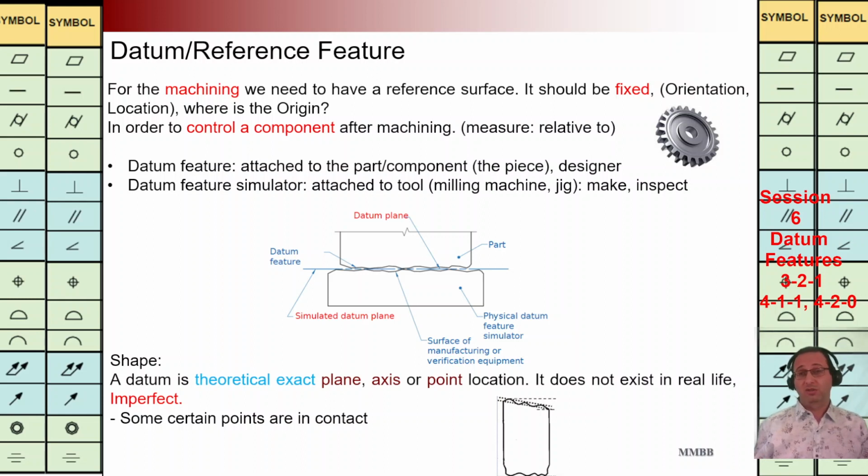Perpendicular to what? Relative to what? Reference to what? In this situation, we need to define a datum feature. The datum feature is attached to the part. As a designer, we are going to attach the datum feature to the part.